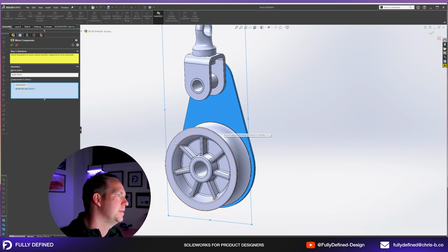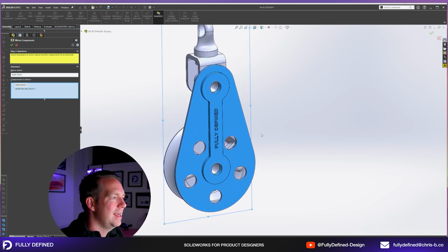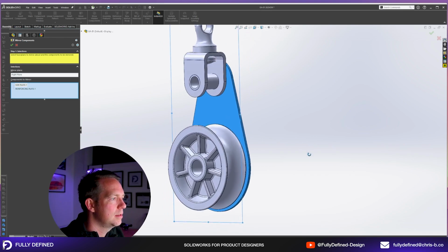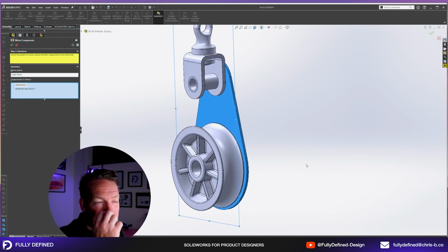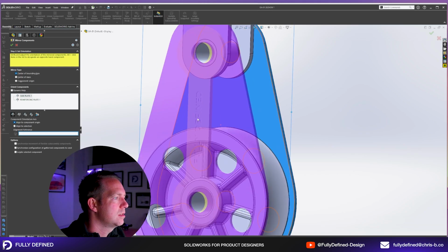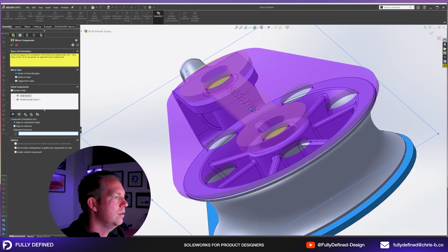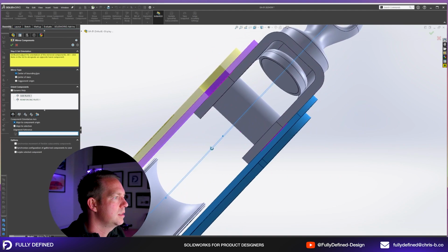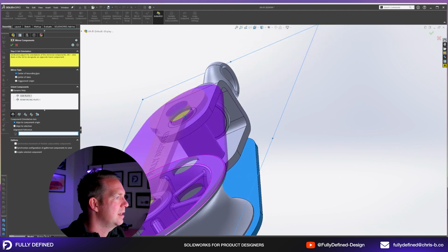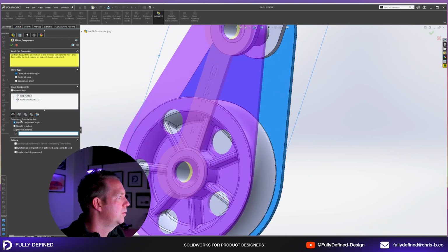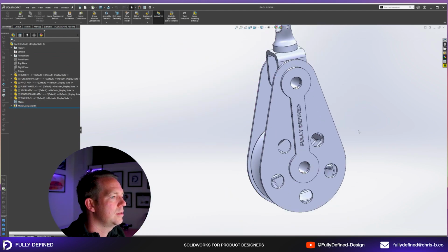So what can happen sometimes is that fully defined text doesn't line up properly on the other side. It's been reversed or upside down or back to front. Best thing here is to press the arrows and keep going through the selections until you can get the right preview. Now this looks pretty good on this example here because the text is on the outside, okay, in that purple preview. So I'm going to press OK, and now that's really good.